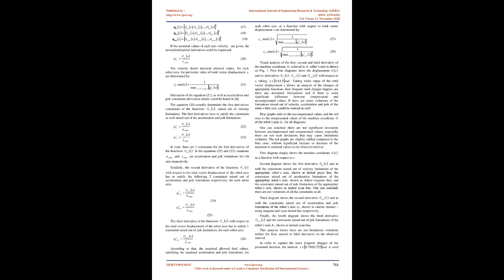Usually an array of desired poses comes as input, and G-code of machine coordinates should be produced in order to send it to the controller. That G-code is produced in some offline procedure such that for every desired pose, the described iterative numerical compensation algorithm is called in order to calculate appropriate compensated machine coordinates, based on calibrated values of the robot parameters, no matter what kind of parametric calibration procedure is performed to derive such calibrated robot parameters.